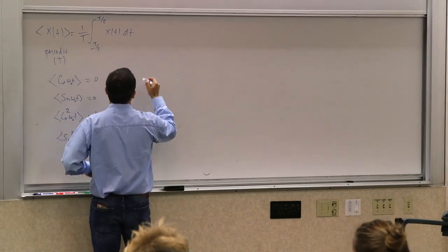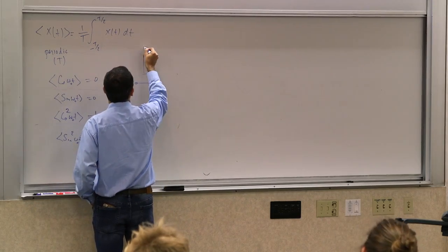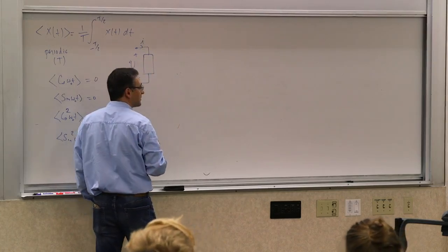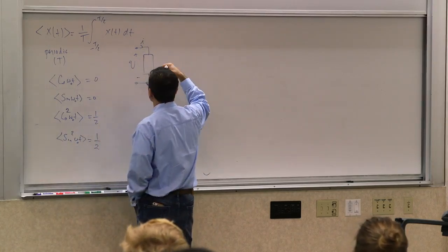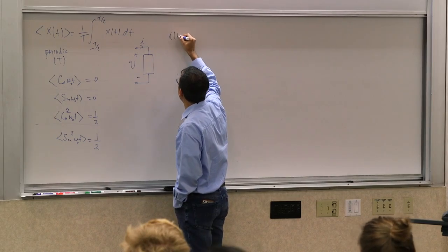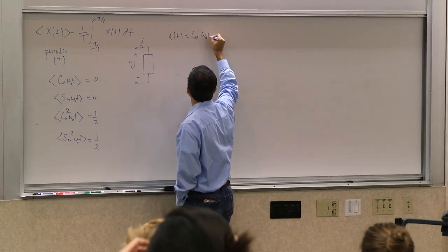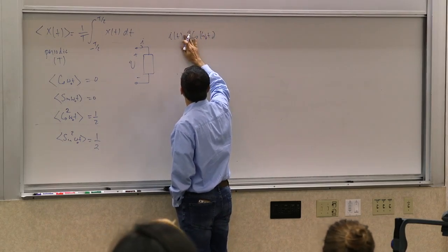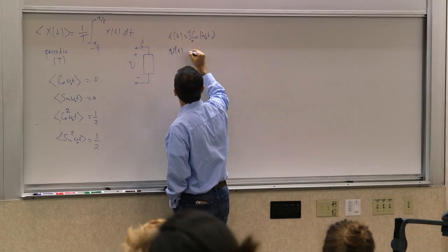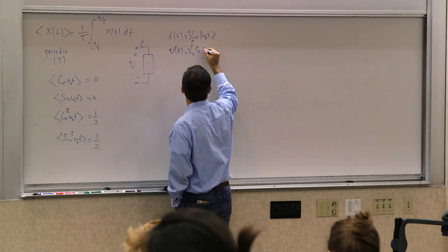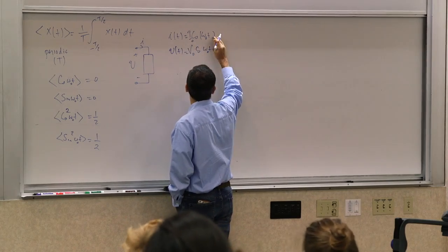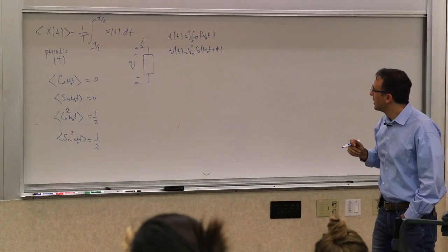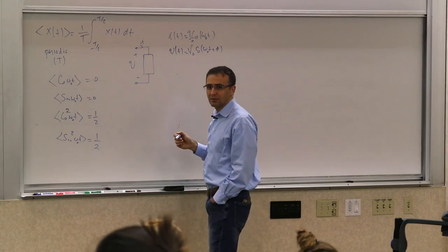but one thing that's kind of interesting about it is that if you have an element with a current I and a voltage V, and they're both sinusoidal. So let's say we are in this phasor domain. So you have I of t, that's I0 times cosine of omega 0 t, and then you have v of t, that's V0 times cosine of omega 0 t plus some phi, because in general, they would not be in phase, as we've seen in several examples. What is the power delivered?